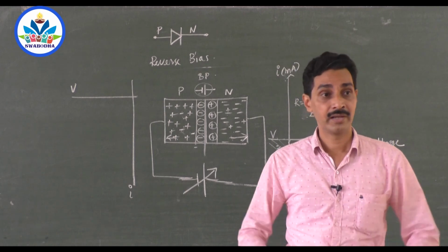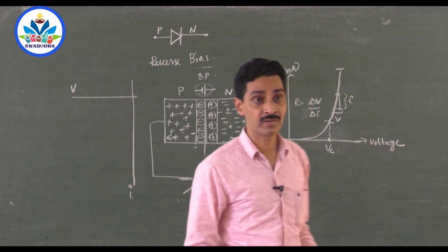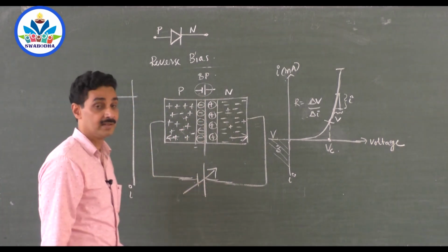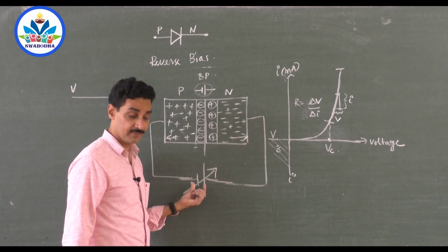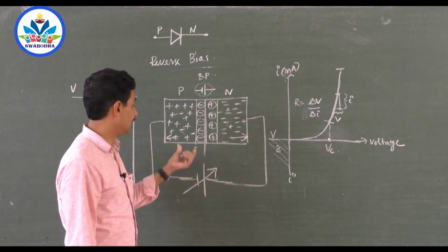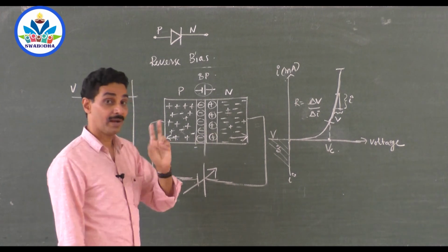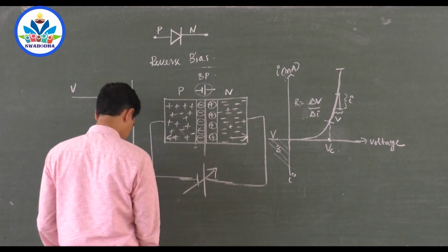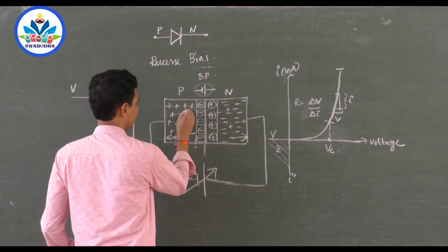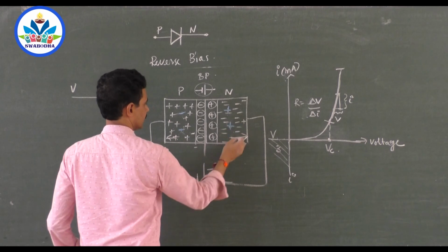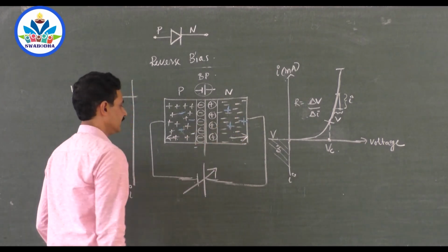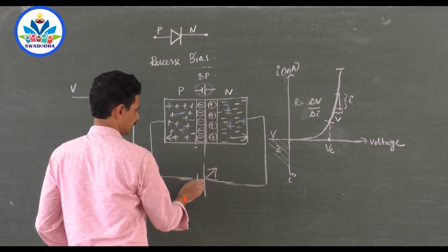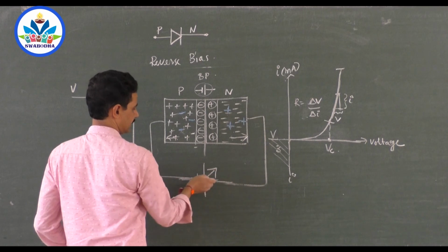How come, sir? Reverse bias is avoiding the migration of electrons and holes, similar to the barrier potential, because you see the polarity, they are very similar. But when this reverse bias voltage is too much, these electrons and holes which are minority carriers can move. What are minority carriers? Here, negative, minority carriers. See, they are having now a very good time because this positive may be attracted by this negative. This negative may be attracted by the positive.